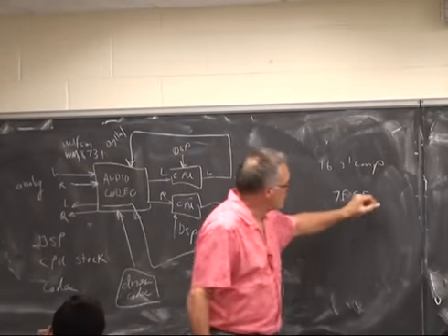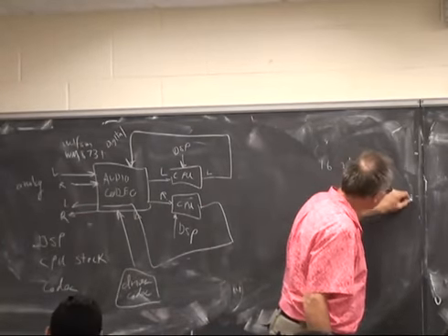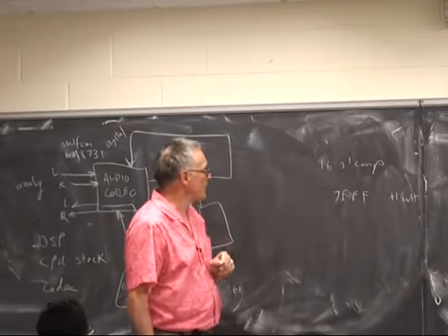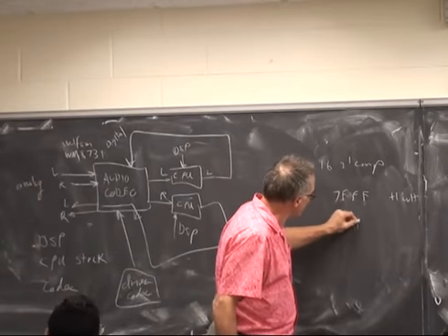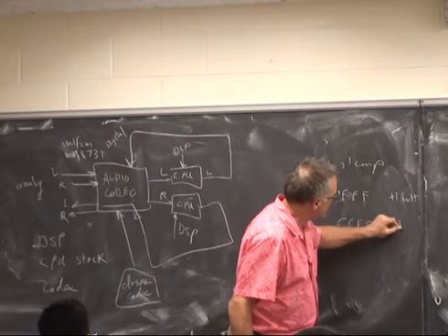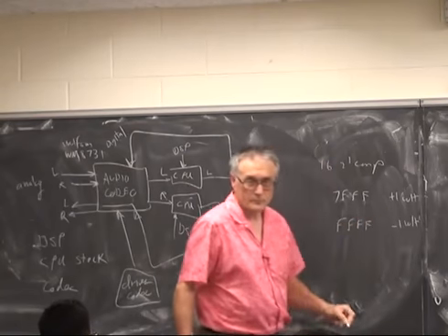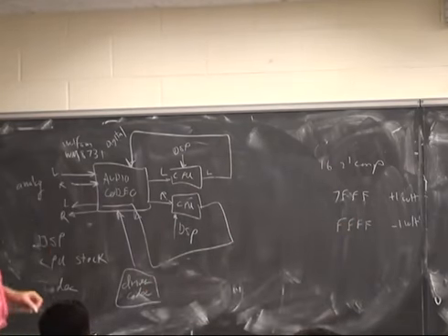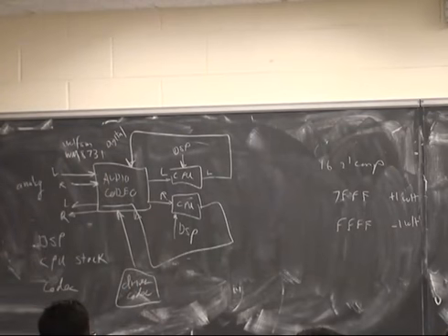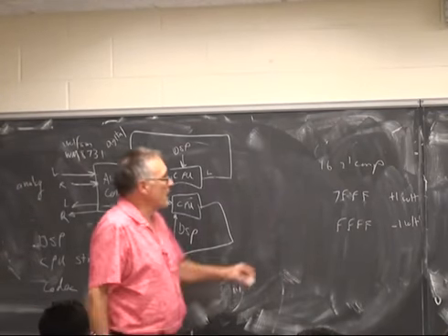That would correspond to plus 1 volt at the output, and FFFF would correspond to minus 1 volt. So it's 16-bit 2's complement.